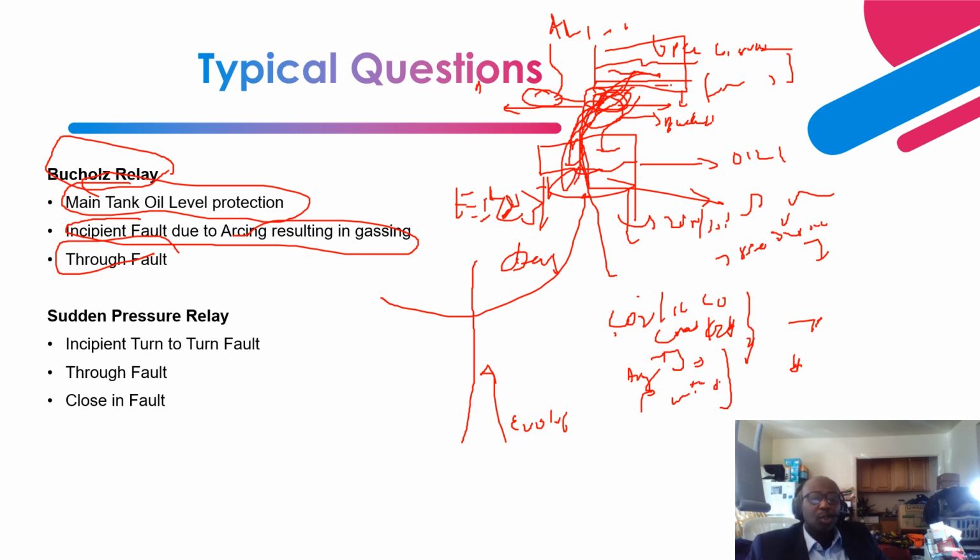backwards. So at the very lower section, there's a vane or a flap inside the Buchholz device. That flap basically moves backwards if the high pressure oil impinges upon it, then it activates a micro switch to trigger the transformer.